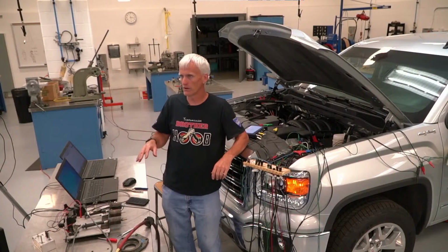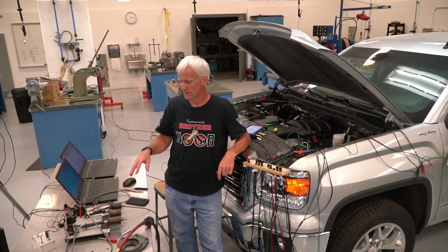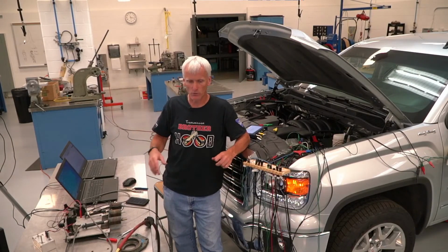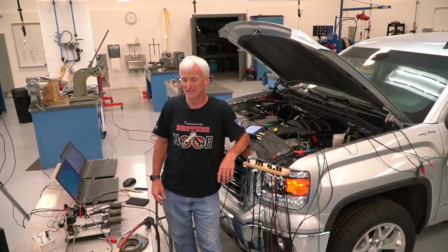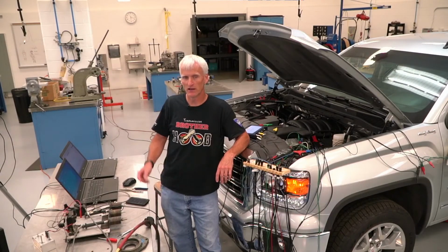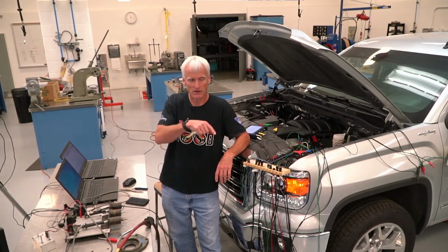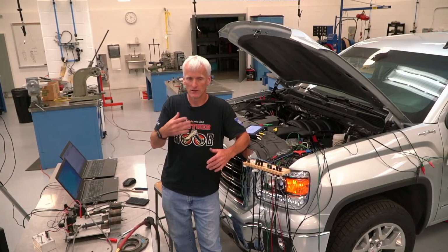I did not go through and cover what would happen in this situation, like with a rich or a lean or carbon fouled plug or anything like that. I don't have any of those examples to show you. You can usually see that in the spark line. It takes a real keen eye to be able to look at a secondary ignition and say, yes, that one is a little lean, that one's a little rich.